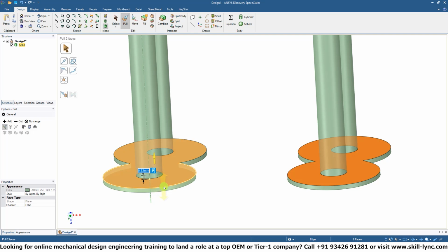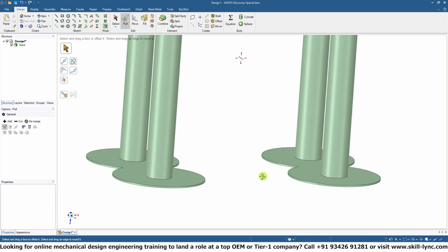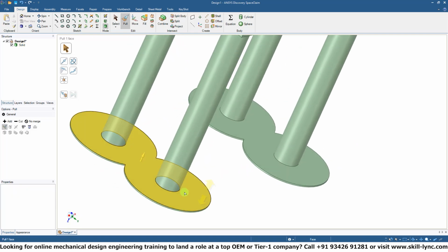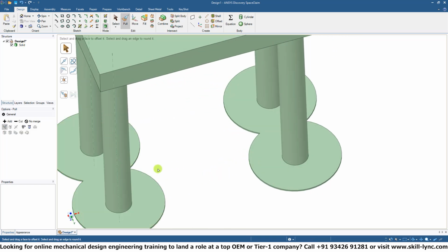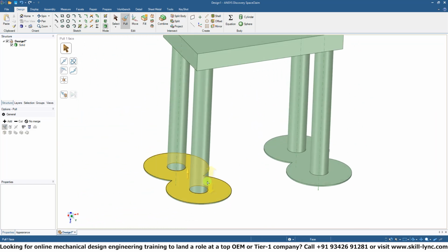Previously, what we had selected was just the perimeter, so it only extruded the perimeter, whereas now we're actually extruding the whole surface area. So now we've created, as you can see, a little plate or a little area of contact for the build plate between the model and the build plate. And this would provide us better adhesion. Now, if the model is knocked at this area, all of the surface area in contact will resist that motion rather than the small area of contact that we had originally.